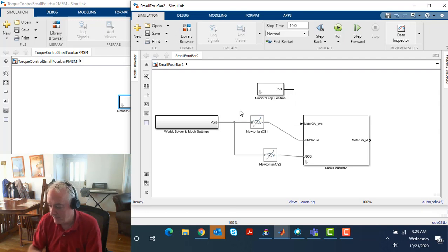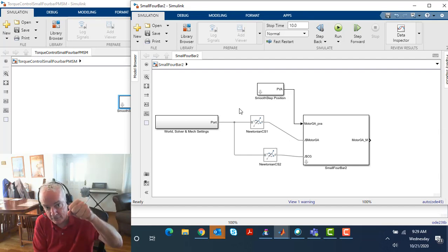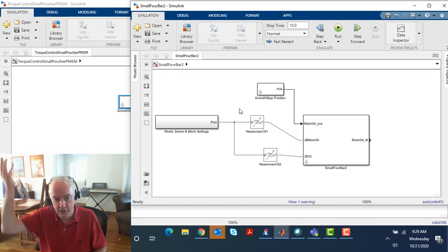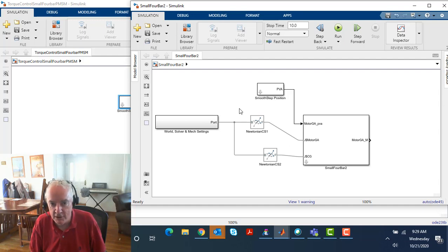Okay, 0.25 meters. So it's based on how much those parts weigh, how that mass is distributed through the shape of the part, but it's also dependent on how we're moving it. And the faster that we want to move it, and more specifically, the faster we want to accelerate it, the more torque required to do that. And of course, we've got gravity acting in this, and that's why it's just essential to have a good mechanical simulation tool so you can understand these things.